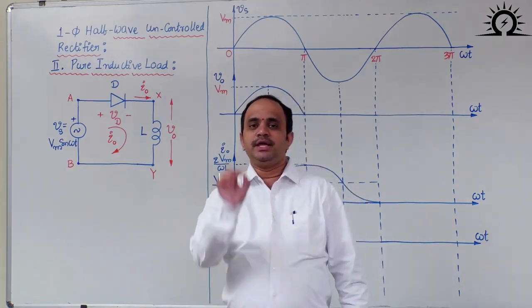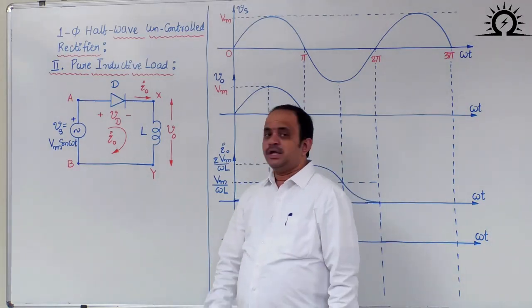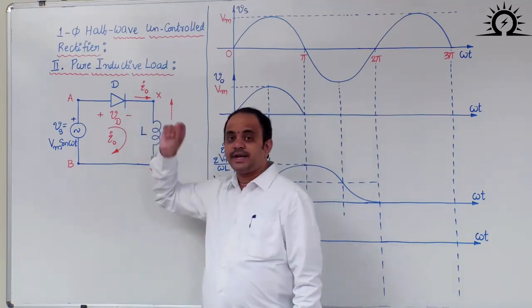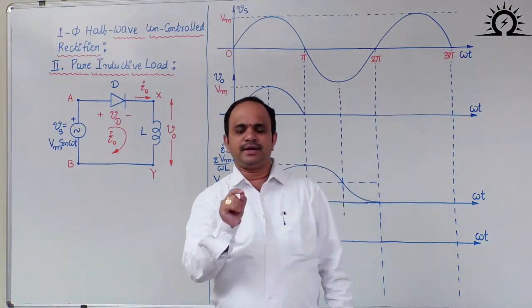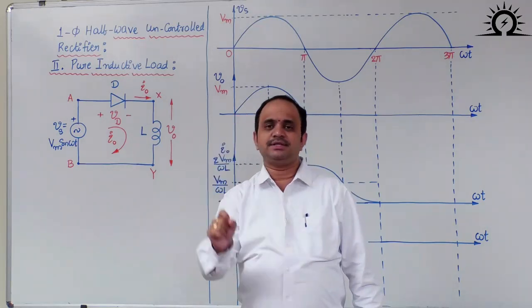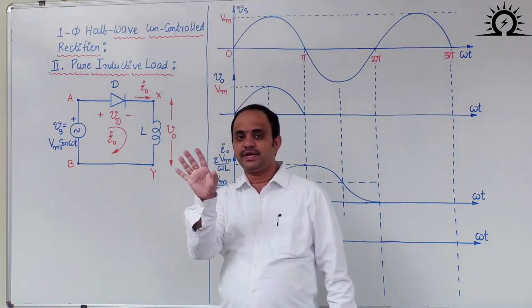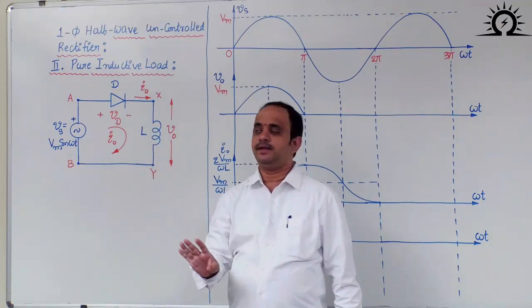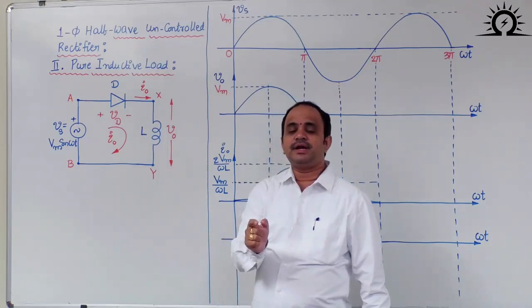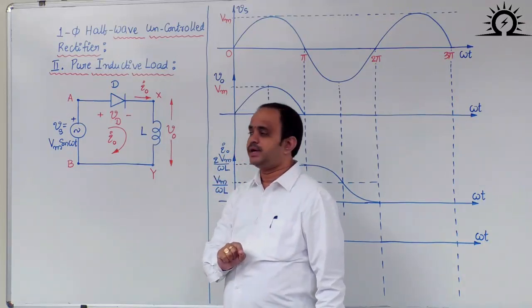Okay. So in rectifier circuits, remember, in entire rectifier circuits, negative load current is not possible. Why? Because in rectifier circuits we use either diodes or SCRs. They are unidirectional switches, from the switches class. Okay, they cannot carry negative current. We are neglecting reverse recovery currents. Reverse recovery currents are not in the discussion at all. Therefore, negative current is not possible. Okay, but negative power direction is possible with negative voltage, right?